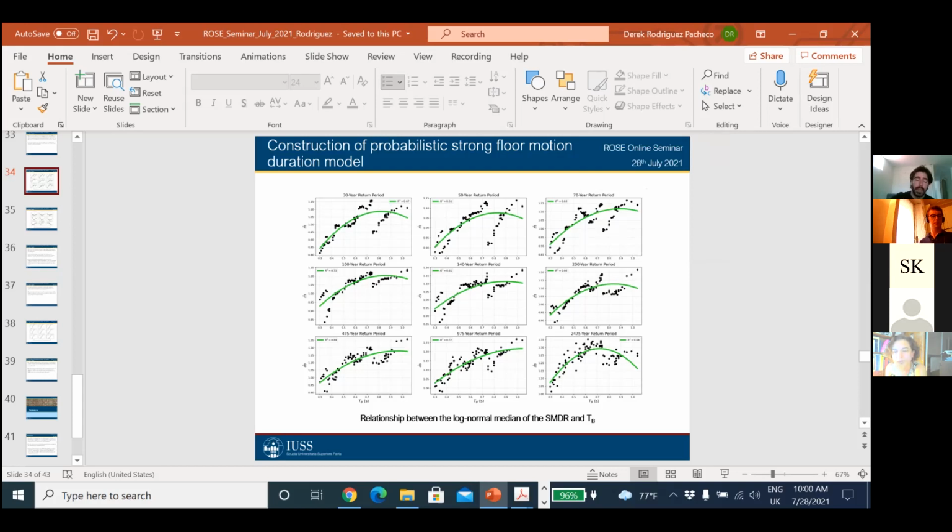Am I right? Yeah, that is actually very true. This is a big problem with non-structural elements. This was also a big issue at one time with structural systems, with seismic performance factors for structural systems. After FEMA P695 was published, this issue got better, since this standard gives a standardized way to calculate performance factors. It makes the process more reliable, and it gives the use of these factors a strong theoretical background.